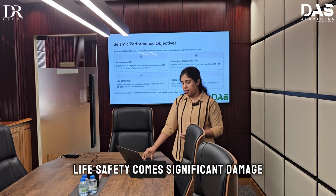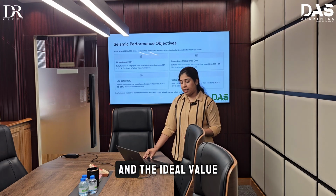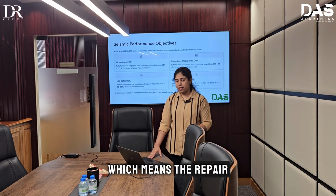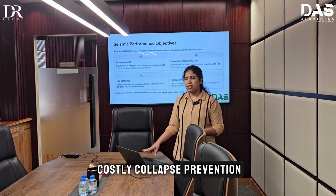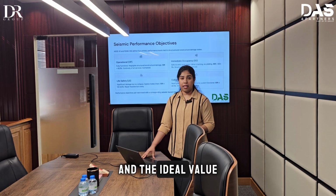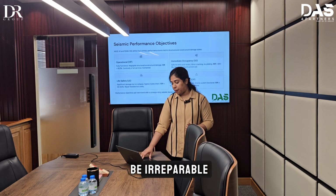Life safety comes with significant damage but no injuries or collapse. Egress routes are intact and the IDR value should be between 1.5 to 2.5%, which means repair is feasible but will be costly. Collapse prevention is near collapse, with major damage. The gravity system will still be functional, the IDR value will be less than or equal to 4 to 5%, and the structure may be irreparable.